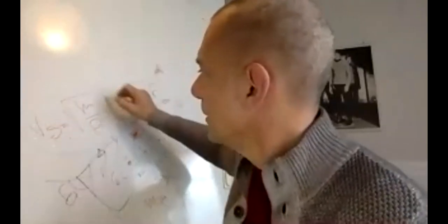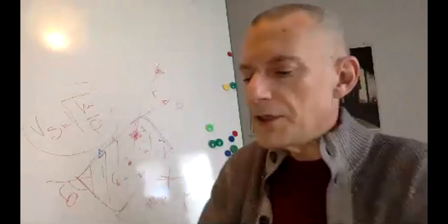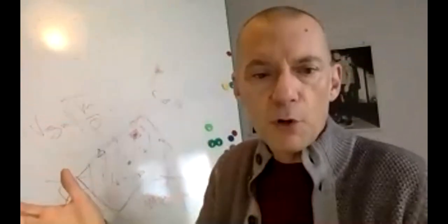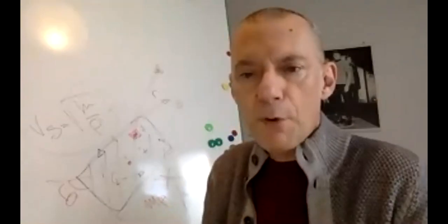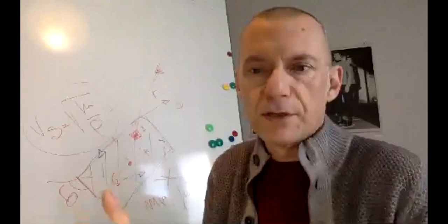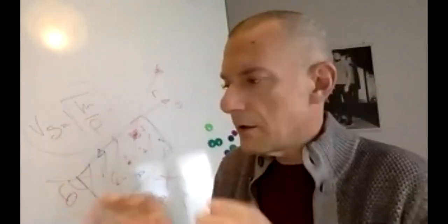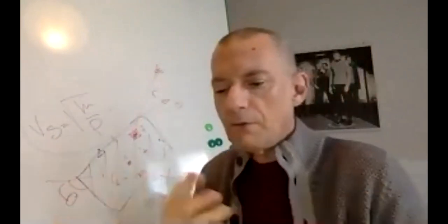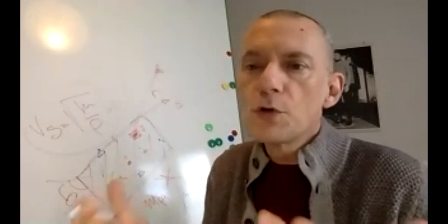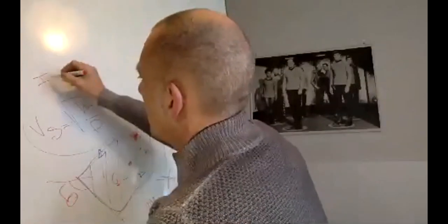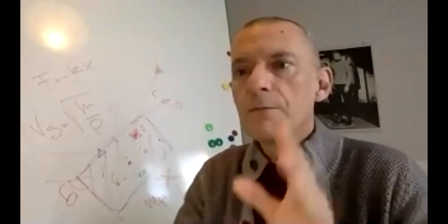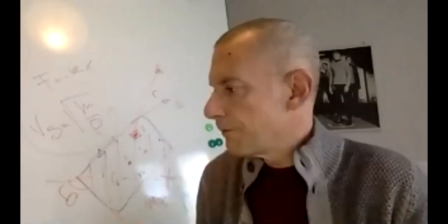If you take this velocity here, the standard one, it's given by a ratio of an elastic modulus, in this case a rigidity modulus, divided by some inertial properties, but of course they are related to density. As you see, that's a tiny and clean definition. And the key is here in the mu, that is a generalization of Hooke's law. Hooke's law relates force and displacement, but when it is generalized, it relates stress and strain.